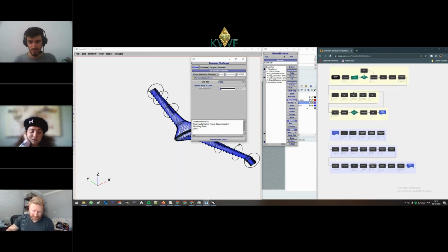Yeah, because anything, at least from my experience, anything that can be done to isolate the primary surfaces like the lifting bodies and anything that can be as true to the original geometry as you can, then a program like OpenVSP that is using the airfoil definition and making a really smooth curve through those points, it's effectively the most accurate representation of the airfoil. If you can avoid any type of rounding, any type of interpolation in the next step, then you're going to be much, much closer to that in the final design.